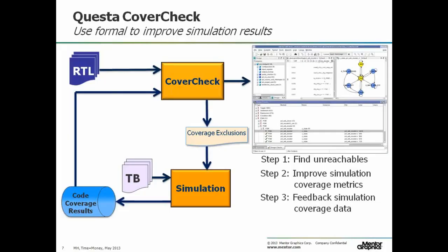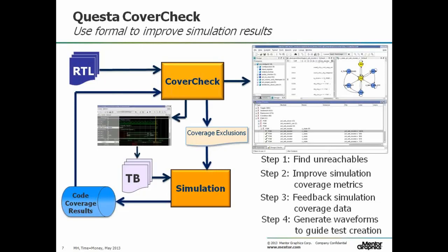If it is reachable, then demonstrate how it can be reached. So provide some stimulus, some examples, some waveforms of how you can do that. If it's not reachable, then again, provide some exclusions so that you can make more accurate measurements of your coverage.